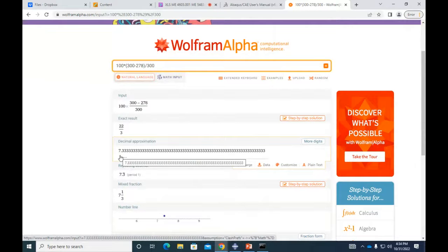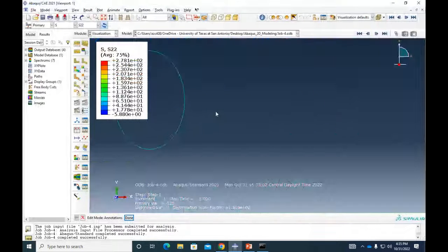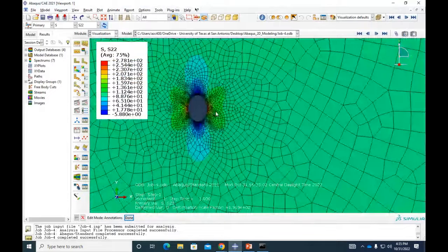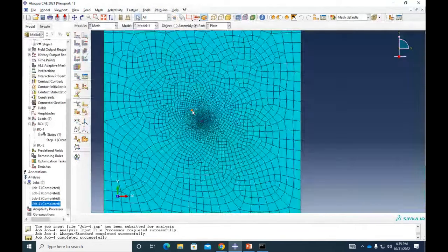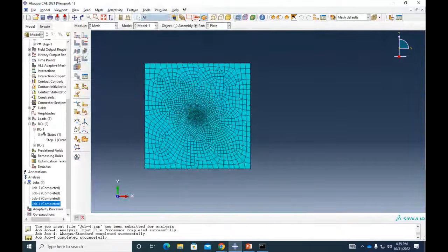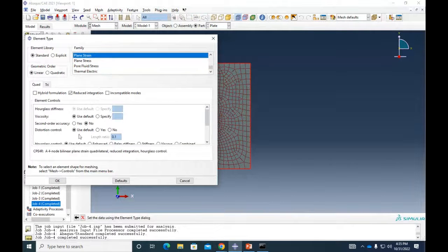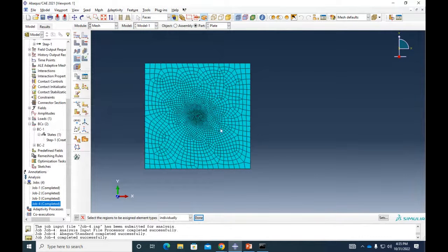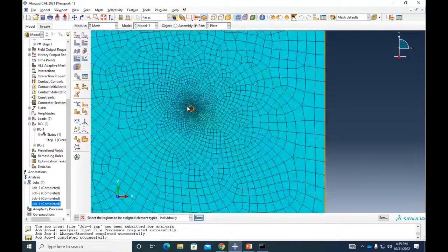All right, so it's still really good. Let's try to take it under, let's say, 1%. So with this mesh, we're not gonna be able to. All right, so let's go here to mesh. We're not gonna be able to do it with this particular mesh. We have plane stress. Okay, doesn't matter. Let's do a smarter mesh, and let's create some beautiful partitions in here.